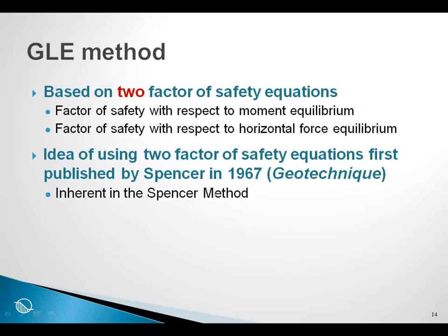The GLE method is based on two factor of safety equations. We have one factor of safety equation with respect to moment equilibrium, and we have a second factor of safety equation with respect to horizontal force equilibrium.